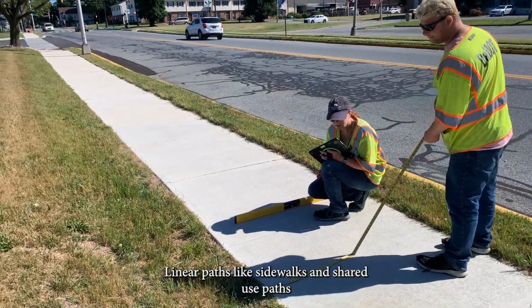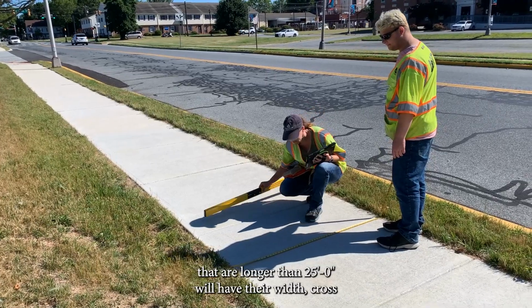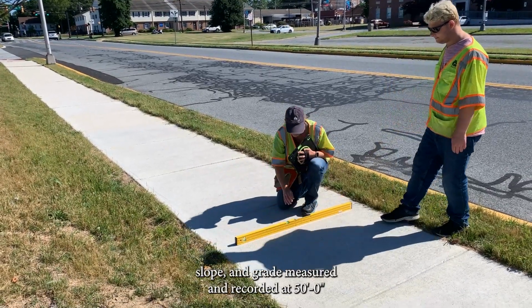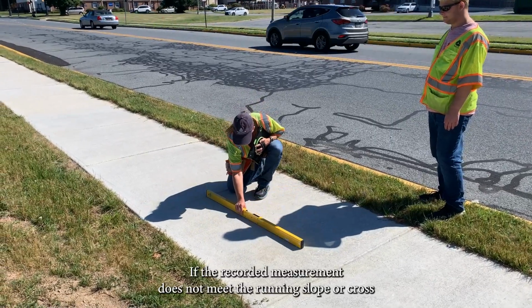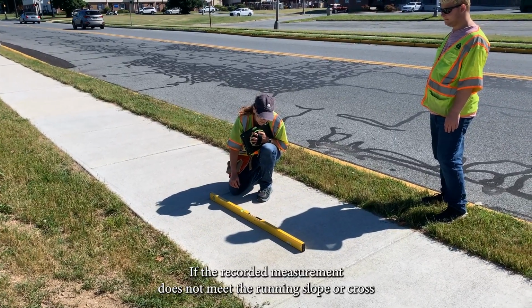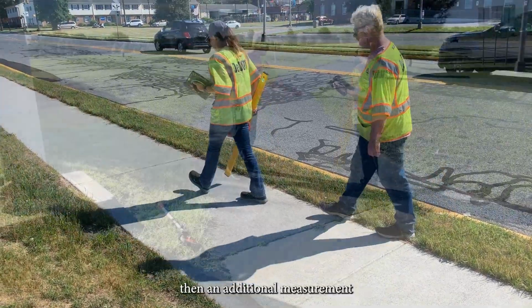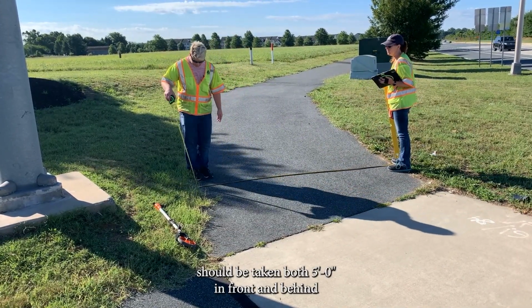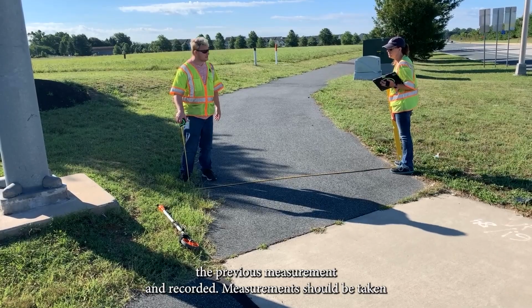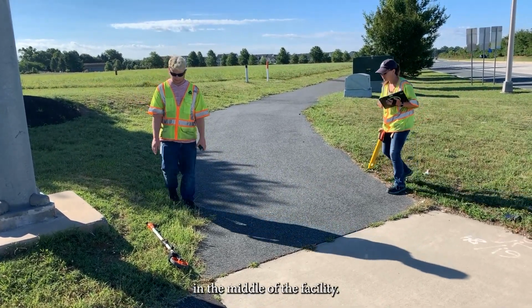Linear paths like sidewalks and shared use paths that are longer than 25 feet 0 inches will have their width, cross slope, and grade measured and recorded at 50 feet 0 inch intervals. If the recorded measurement does not meet the running slope or cross slope accessibility standard at that increment, then an additional measurement should be taken both 5 feet 0 inches in front and behind the previous measurement and recorded. Measurements should be taken in the middle of the facility.